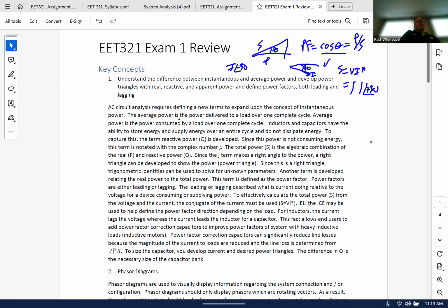So what I was saying is once you decrease the magnitude of S, because you've added a power factor correction capacitor, you decrease the magnitude of the current. So you get less line losses in your system. Your system is more efficient. That's why the utilities charge customers for poor power factor, because they're consuming more watts on the system because of the increased I squared R.